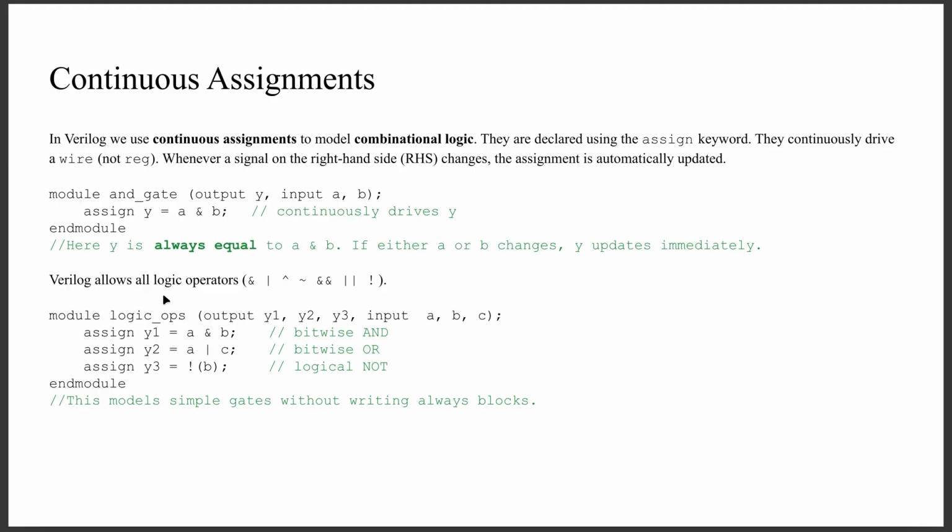Verilog allows all logic operators. So in this module, we have the outputs Y1, Y2, and Y3, and inputs A, B, C. This is what we would do for bitwise AND, bitwise OR, and then logical NOT. So this module implements simple gates without writing always blocks.